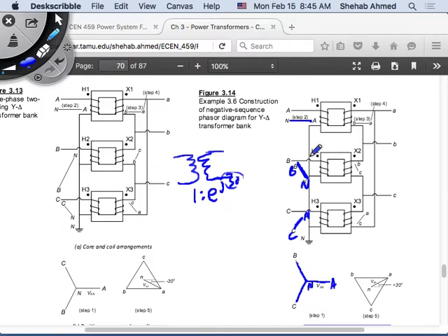And then for a star delta or delta star, you have another problem, which is the angle. What is this value of angle? The value of angle depends on the details of the application. Okay, I'm applying positive sequence on the primary side and it's connecting the transformer in this way. Now I'm leaving the same transformer, but I'm changing the sequence of the voltages on the primary, and I'm applying negative sequence. This will change this thing. The e to the j 30 may be e to the j minus 30.